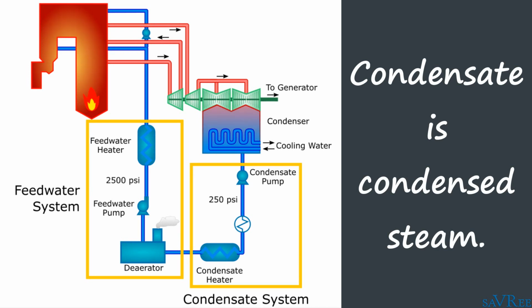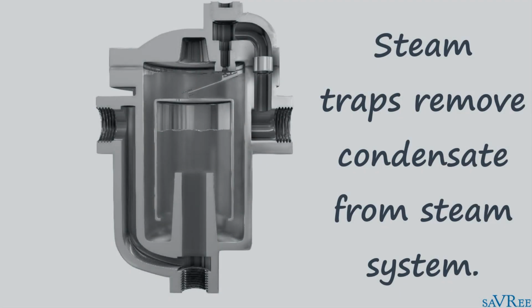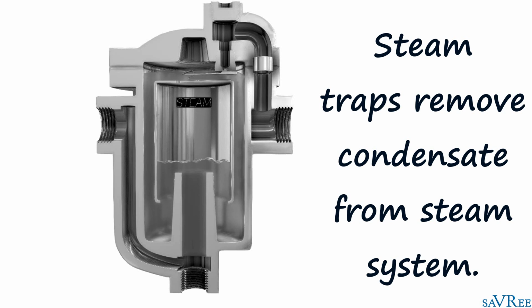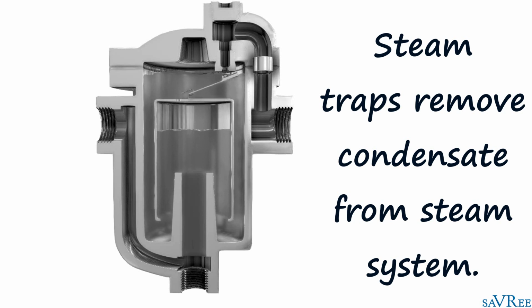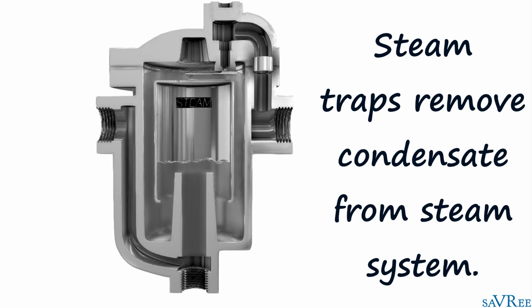Condensate may be gathered at any part of the system and fed back to the deaerator or perhaps even the condenser. Condensate is water. Specifically, it is condensed steam. The steam that we created by a water tube boiler has given up a bit of its heat and it has condensed. Throughout the entire system, not all of the steam will give up its heat at the same time. And because of this, we'll need to have steam traps and drains throughout the entire system so that we can direct that condensate back to a storage area or a deaerator or the condenser.